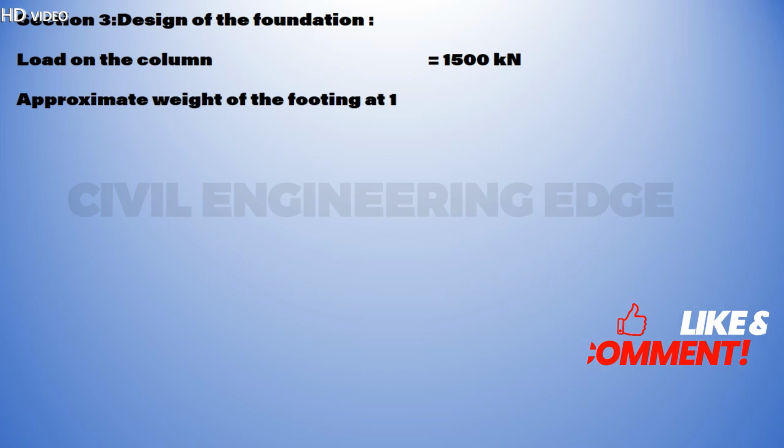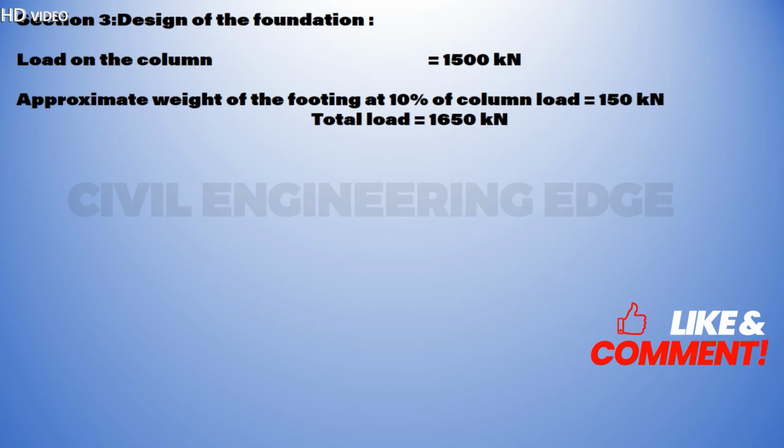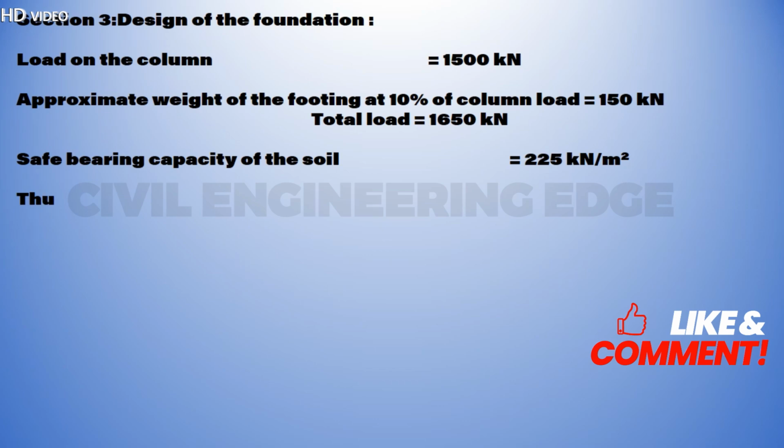Projection beyond the critical section, at the column face, is (2,750 − 500) / 2 = 1,125 millimeter. Maximum bending moment, M at the column face = 198,347.11 × 2.75 × 1.125 × 1.125 / 2 = 345,170 Newton meter.